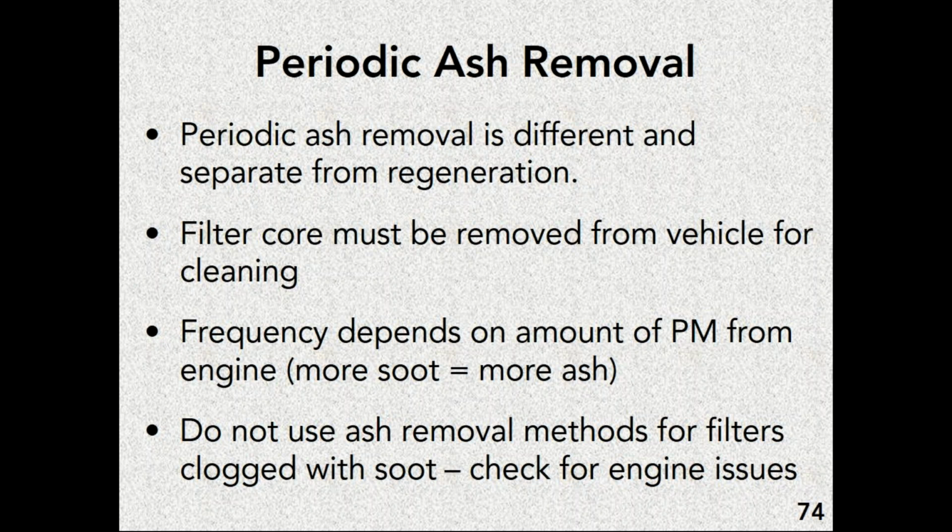So as a consequence of working in those dusty areas and going through regeneration, we're going to have a buildup of the dirt material, although it's burned, but it's still part of that. So we need to be aware of the fact that that's something that can build up inside these filtration systems and periodically has to be cleaned out.